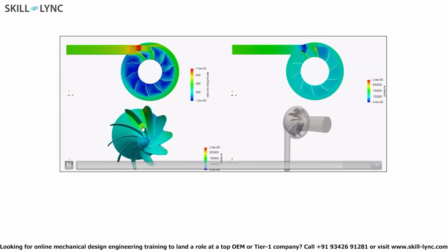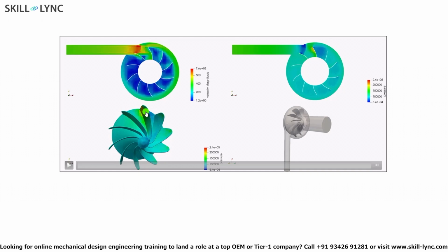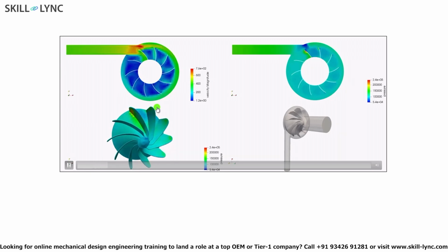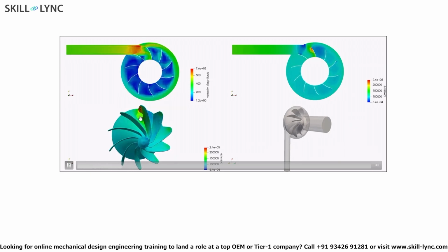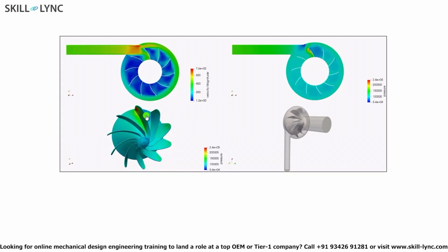So you can take this pressure field and get a pressure force and use that as a boundary condition for a modal analysis to kind of understand how the mode shapes vary at different RPMs, right? But that being said, the simulation is fairly coarse. As you can see, we would definitely need to run the simulation a bit finer if we want to get engineering data out of it.